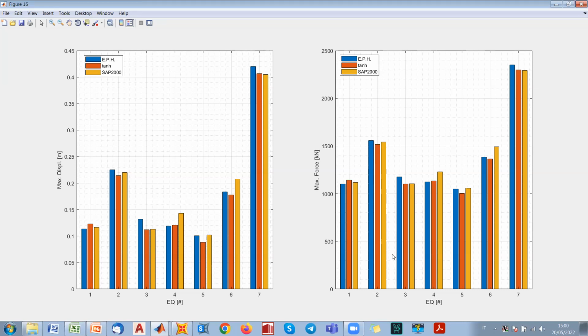Generally, the variations that you can find in displacement response are higher than the variation that you can find for maximum force. You see that here we have approximately the same drawing, but the numerical values are much higher. This means that generally the variations are much lower for the force. So I think that this is it for the curved surface slider, and we go on.